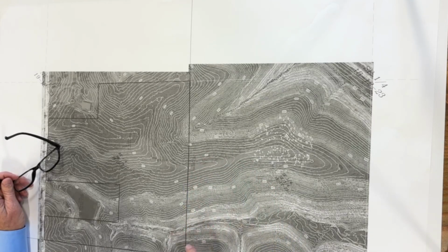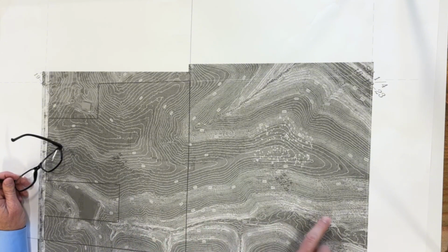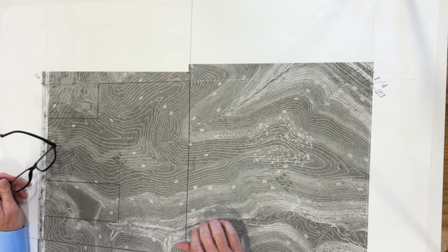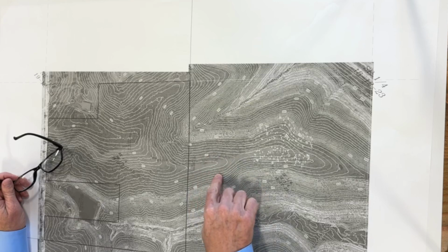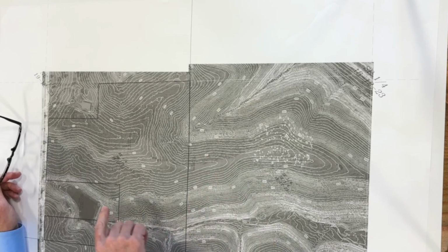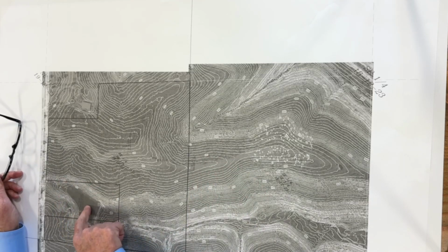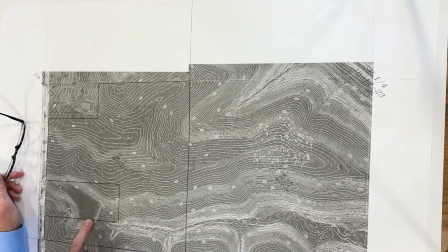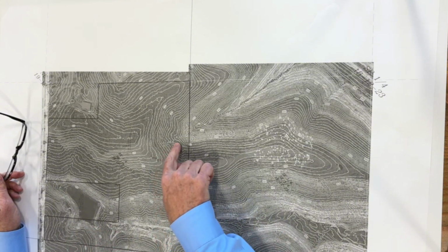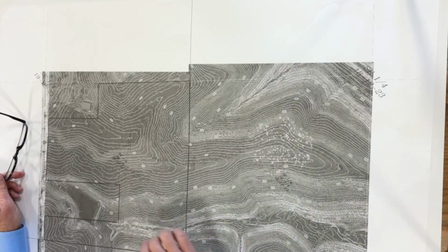numbers, other than when you look at creeks and you see these pointed lines like this. These are classic indicators of creeks right through here, whereas rounded areas like this are classic indicators of ridge lines, because unless it looks like a sharp edge on a mountain, it's always going to have a curve, where creeks will have this. So we know, for instance, we've got a pond right here where the ground is sloping from this ridge down to the pond. It then does the overflow here and goes, and this is where the water goes. And water will go down this creek as well, off of this ridge.